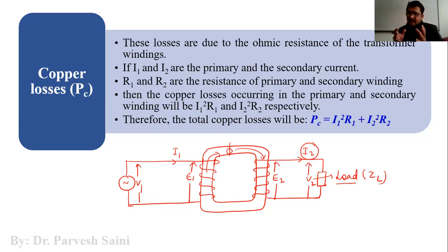Because this current is negligible, we generally do not consider the winding losses, right? But when the transformer is loaded, the current in both windings is assumed to be flowing at the rated value, so now we cannot ignore the losses in the windings of the transformer because of the resistance and reactance of the primary winding. So this is, let us say, R1, this is X1.